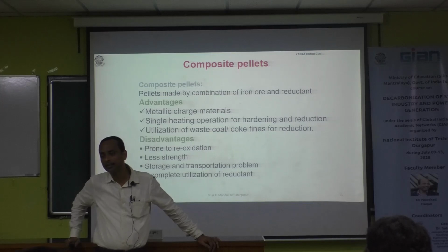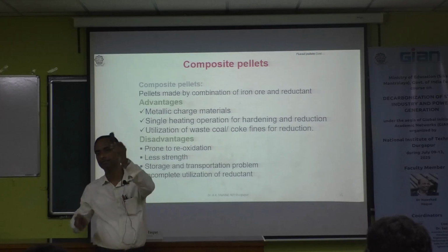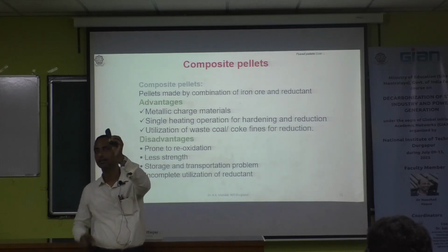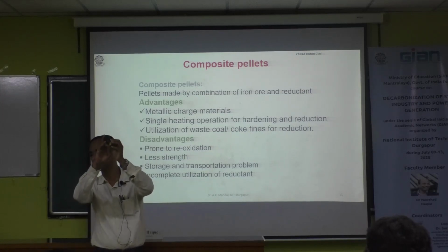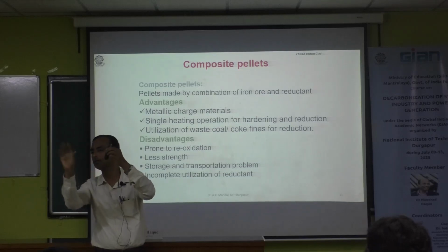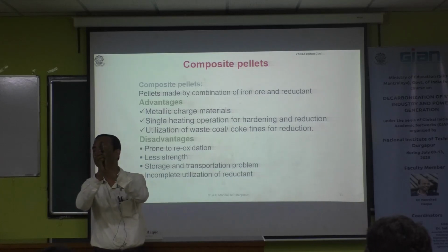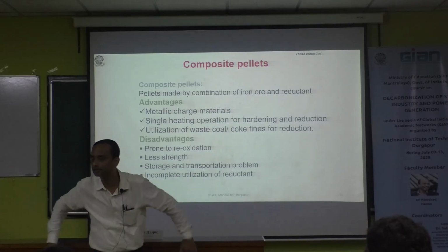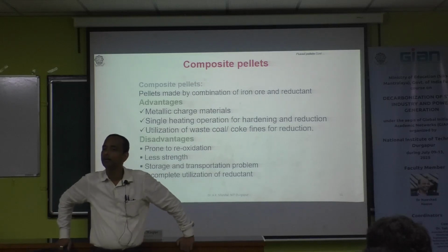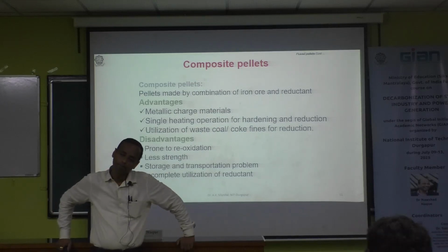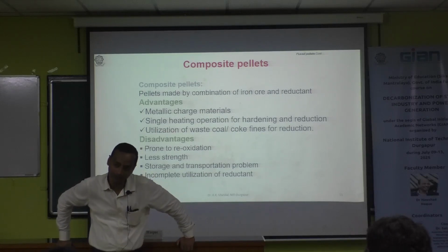Can you repeat the question again? Suppose this is a pellet. 10 gram Fe2O3 is there. And to reduce this 10 gram Fe2O3, X gram carbon is required. I incorporate extra carbon and make the composite pellets and reduce it. A layer will be formed over it, over the surface. That will prevent further reaction. And this will be for the gas diffusion model.